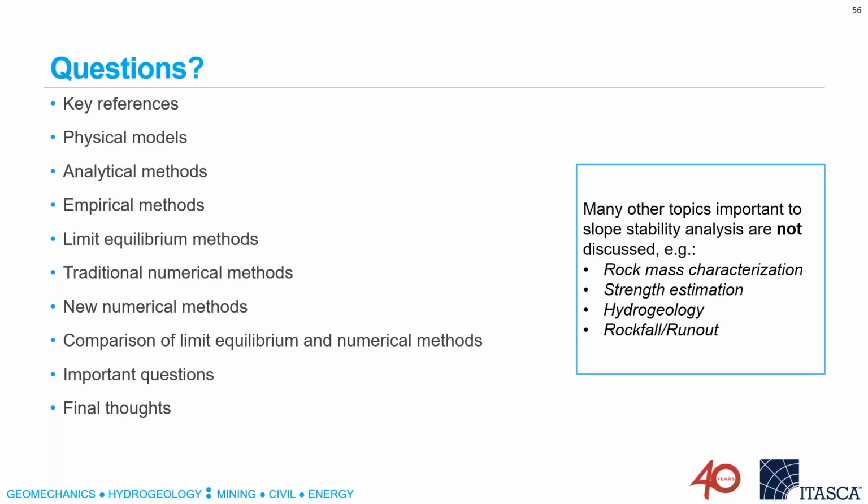So the other evidence that we have, and probably the biggest evidence that we have about what's the right way to go about this, comes from looking at failures. And when you look at failures of slopes, the first thing you see is that by and large, they're fairly shallow. They very seldom exceed 100 meters, even in the biggest slopes, and most often they're less than 50 meters.